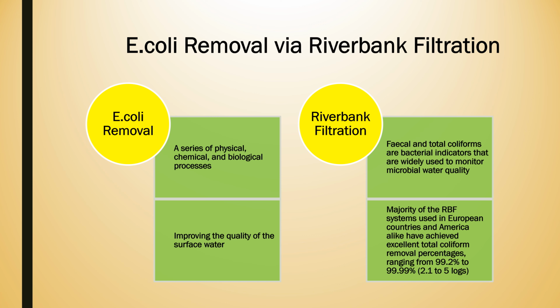The majority of the RBF systems used in European countries and America alike have achieved an excellent total coliform removal percentage, ranging from 99.2% to 99.99%, or 2.1 to 5 logs.